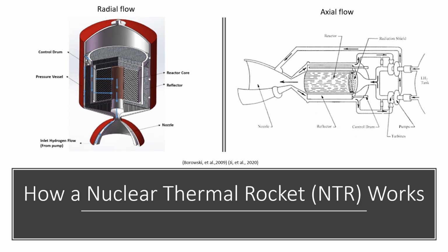Now, in both designs, as the hydrogen passes through the hot gas channels, the temperature of that hydrogen is expected to reach up to 3000 Kelvin. Now, reaching those kind of temperatures, the hydrogen gas is obviously superheated and gets really excited. That excited gas accelerates and gets compressed in the convergent-divergent nozzle, which essentially causes the propulsion of the system.